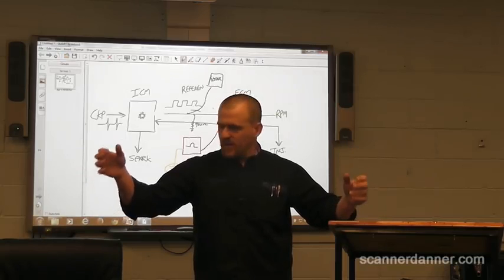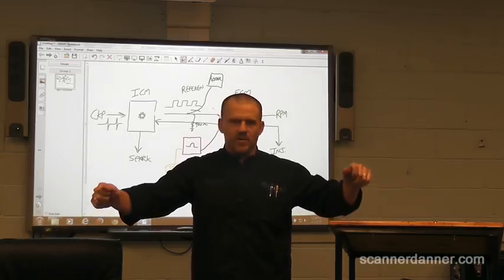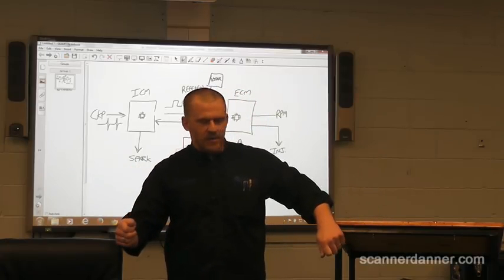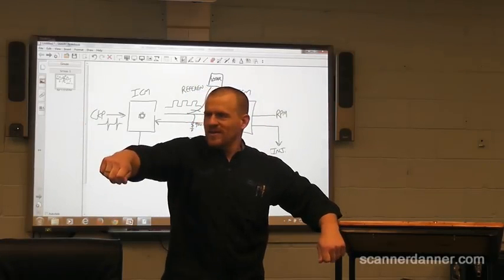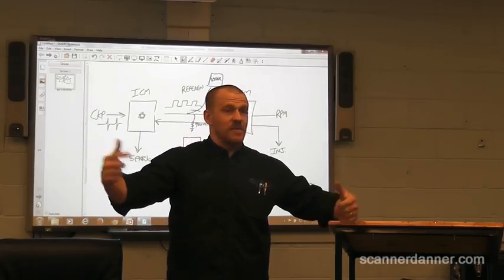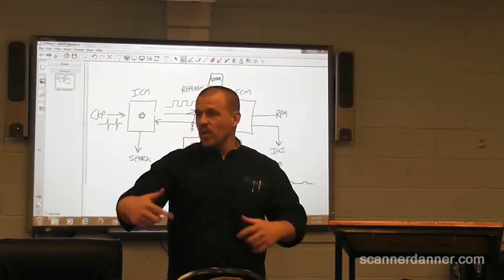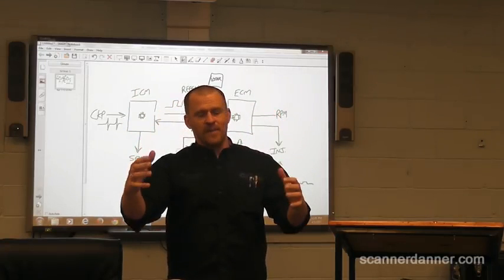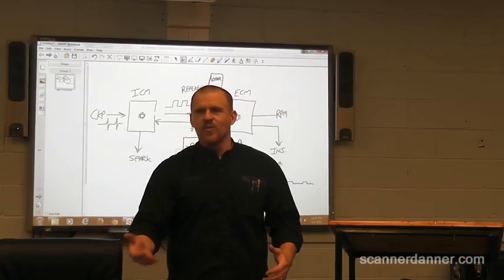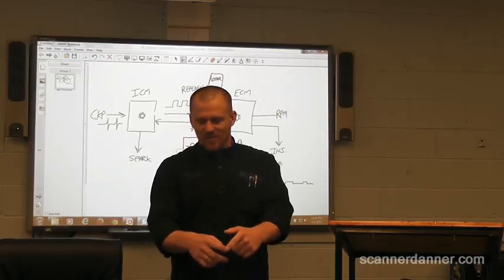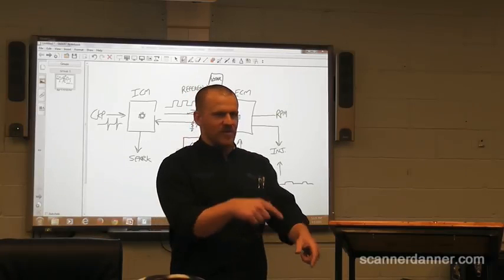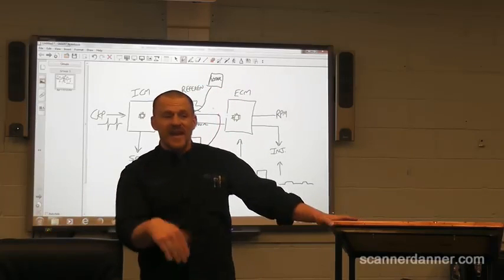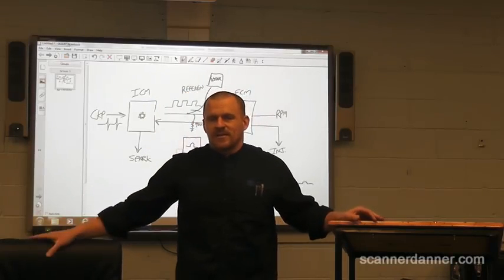If I hold the positive lead here and the negative lead here, imagine that you're connected to a ground and you're touching the lead as you're touching maybe your T-pin or whatever it is you're measuring, and you want it to read OL, the highest scale, and what's happening is you're getting some reading on your meter. What is it doing? It's traveling through your finger, up your arm, across your chest, down your other arm, giving you a reading on the meter. So on your megohm scales, don't touch the leads. That's all.